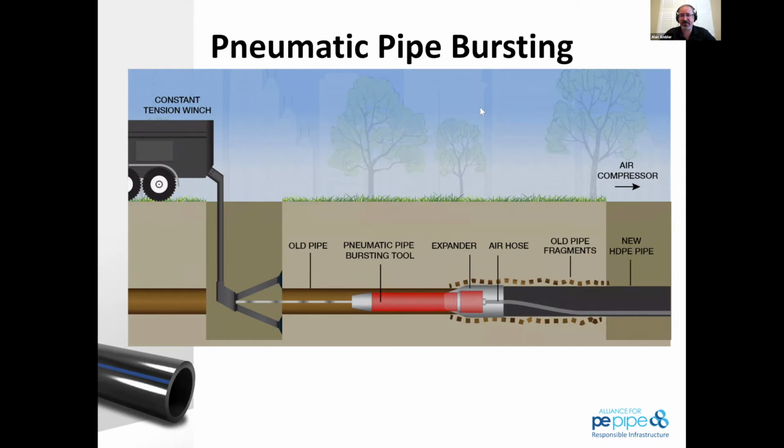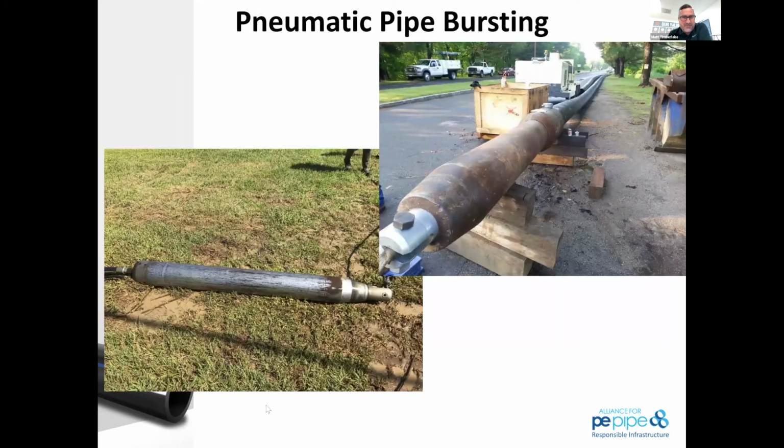Another thing in pneumatic pipe bursting that you can do, since you can use the actual manhole to daylight the bursting equipment, sometimes you can use a reversible tool to eliminate yet one more excavation for you. So. Yep, and we'll show you some good pictures of those. But yeah, those are good questions. As we progress through, hopefully those will start to answer some of those questions. Go ahead and progress forward.